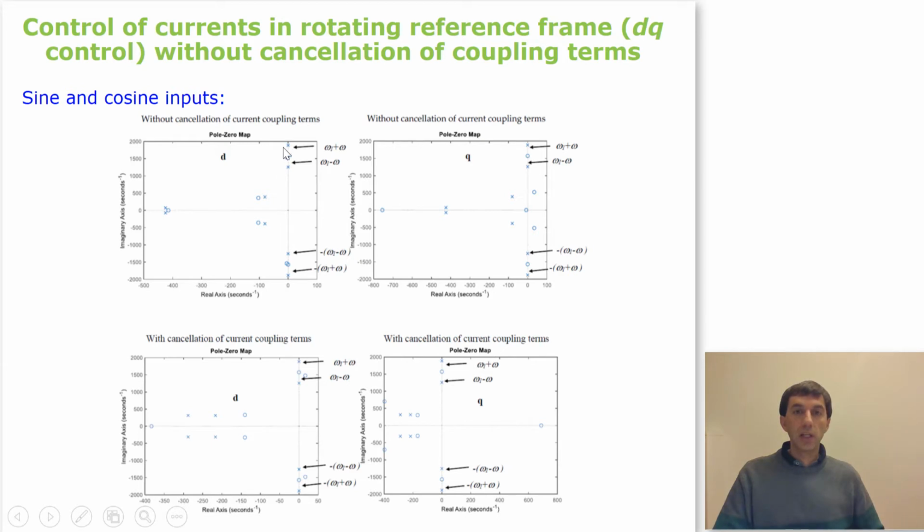Again, we have the steady state in both, and we have the transient response or the natural response of the poles, which are at different values in imaginary part and in real part, compared with the previous ones obtained with the control with cancellation, where there was a correspondence. So here again we have an alteration or a different location of the transient response poles.